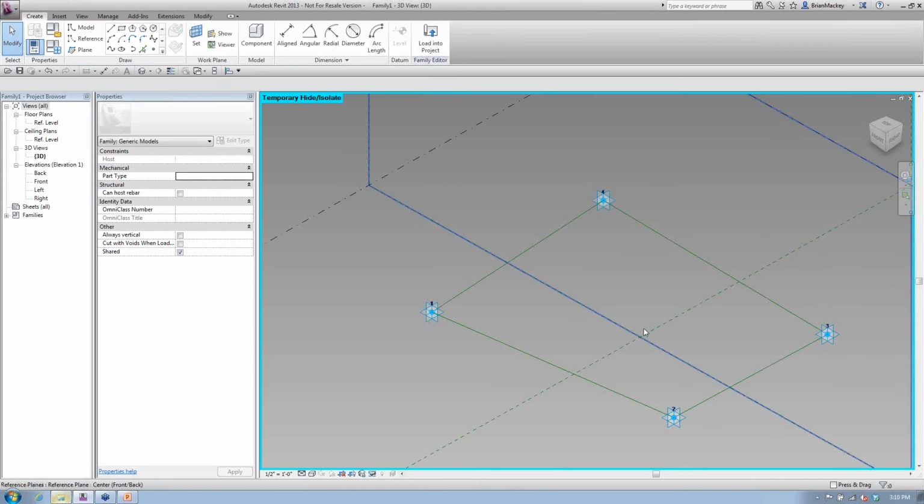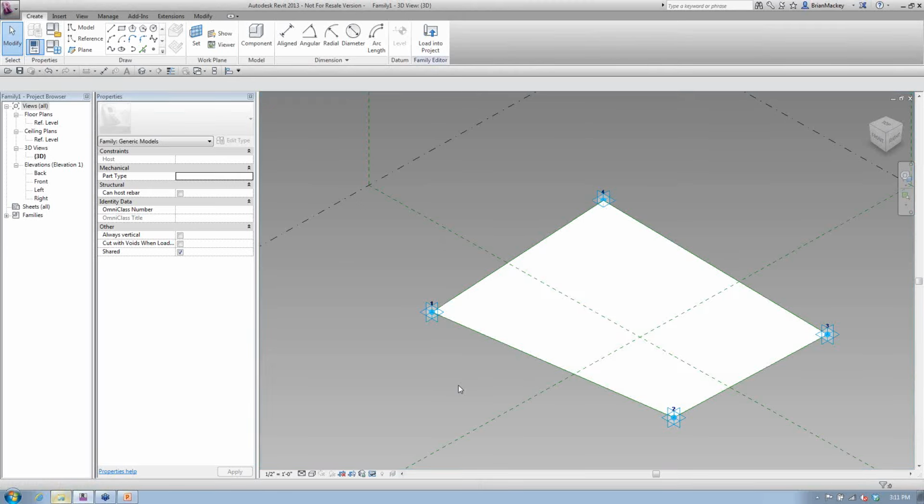But when you start getting to massing, and I talked about this last month, sometimes those model lines will get absorbed into the family. So I can't go back to the beginning and have model lines sitting there, so I don't want to make changes or anything. It kind of becomes a pain. So I always use reference lines, but I forgot that in the adaptive family, not true in the massing family, those get added to it. So great, I've got this 4-point family.